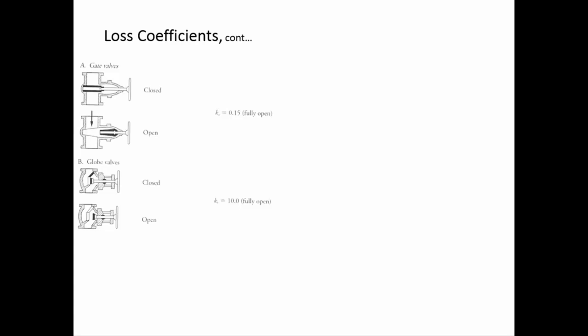And what you're going to be deciding is you're going to be balancing. If you make the pipes big, then the system costs more money. But if you make the pipes really small, then people don't have very much pressure at their house. And so there's this range of acceptable values that you're trying to balance, where you want to make the system as cheap as possible but also deliver required pressure to different houses.